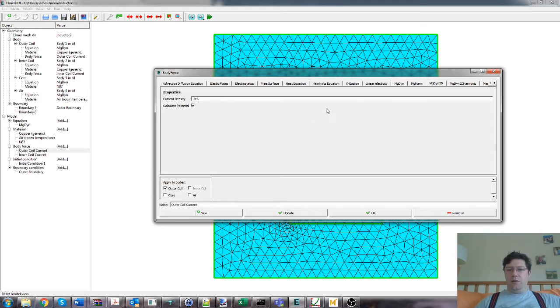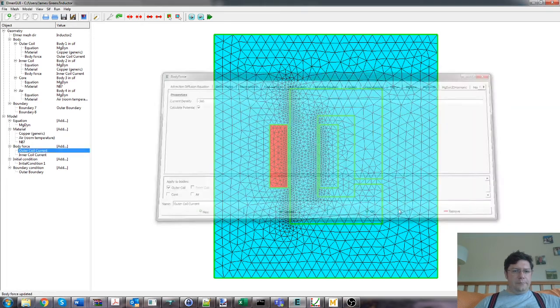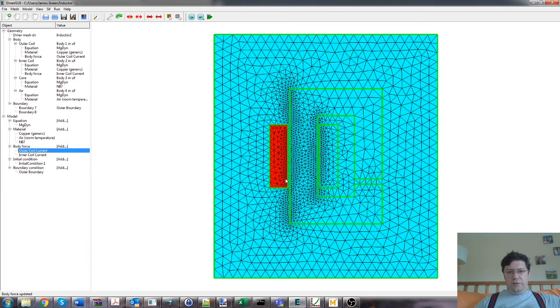If you need to set up a coil, there are a couple of different ways of doing that, and I will discuss them later. So for now, we will be dealing with current densities, which you might argue is not a terribly helpful thing to do, because the first question you get is, how much current is creating the current density? Well, we can deal with that in a bit. I just want to get through the workflow, and then in a later video we'll build it up to something a bit more spectacular. So there's obviously current goes in, current density goes in the page, current density comes out of the page, or possibly the other way around, doesn't really matter.